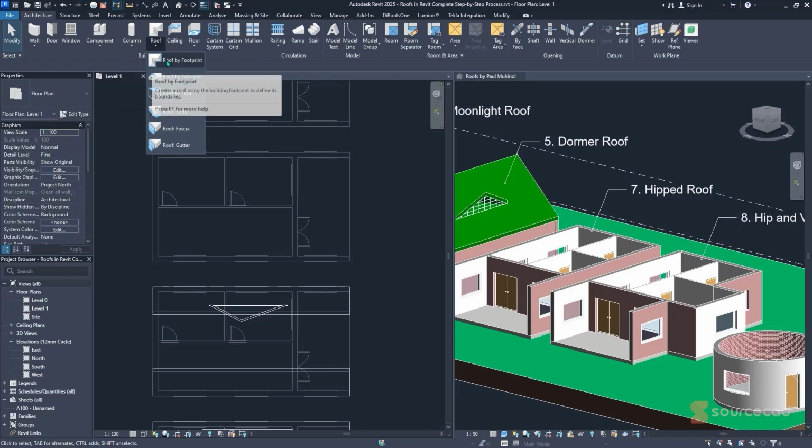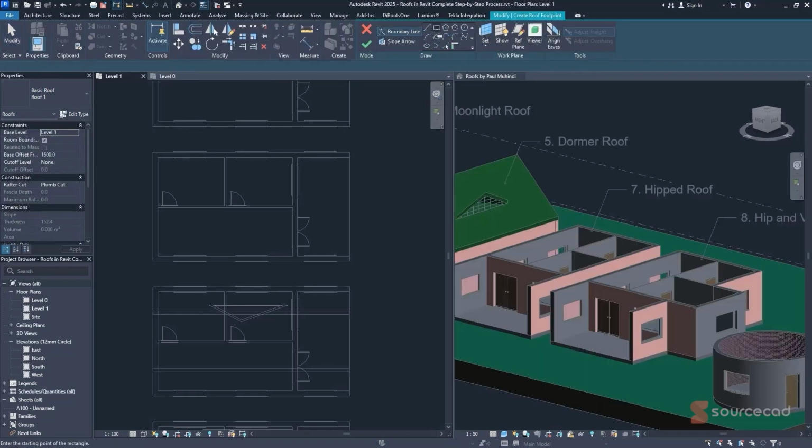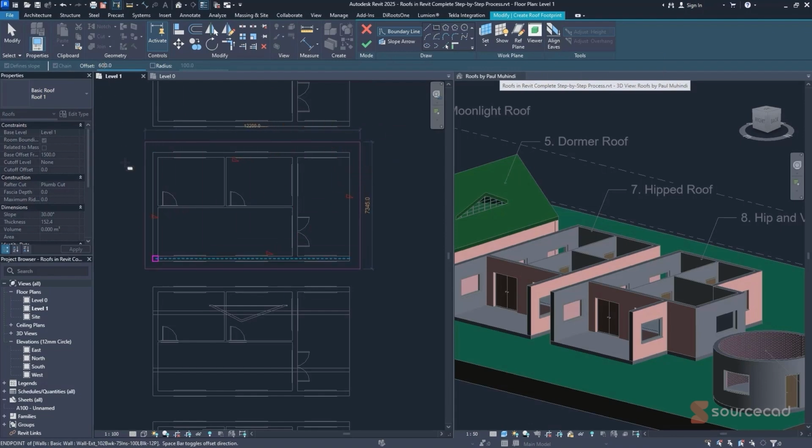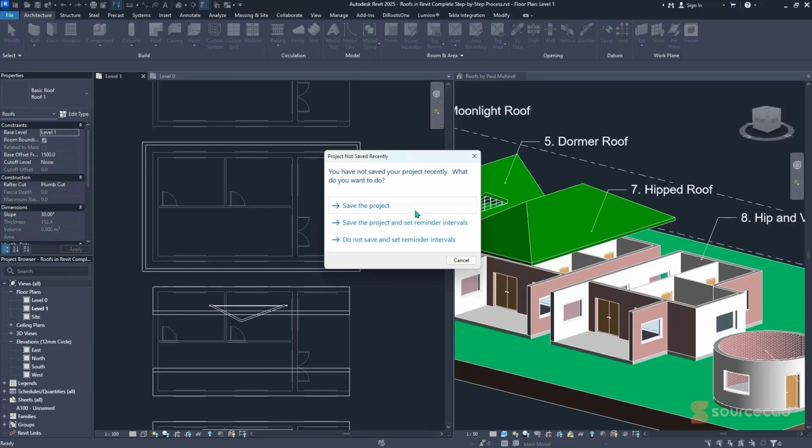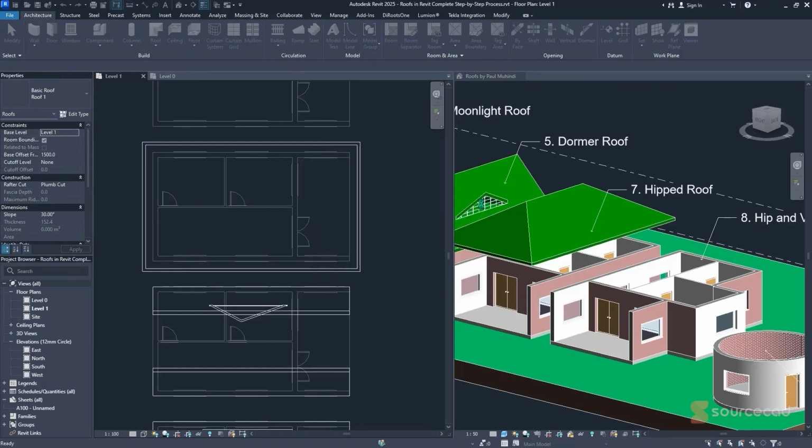It's very simple. I'll just go to Roof, select the roof option, I'll select Roof by Extrusion, then I'll simply select all around this specific building. And for this case, let's add an offset. So this is simply an eave, where we have this eave option, and then I'll simply click away. After that's done, you can just hit finish. If you click on the check option, it's going to be finished.